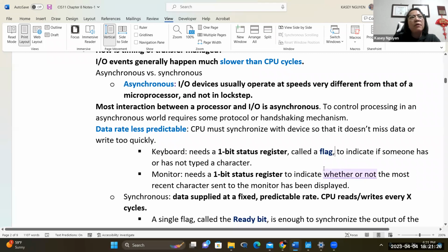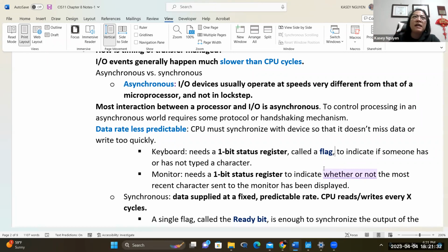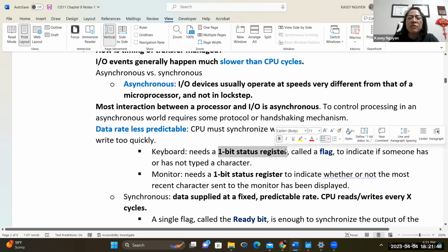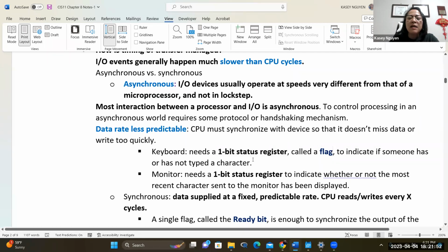If you think about the electrical signal, it would either receive the on bit, mostly close to 5 volts, and when it's not ready, it turns that off, where it drops close to 0. So they simply use that status register to indicate the bit for the flag, to see whether the character was received or not.